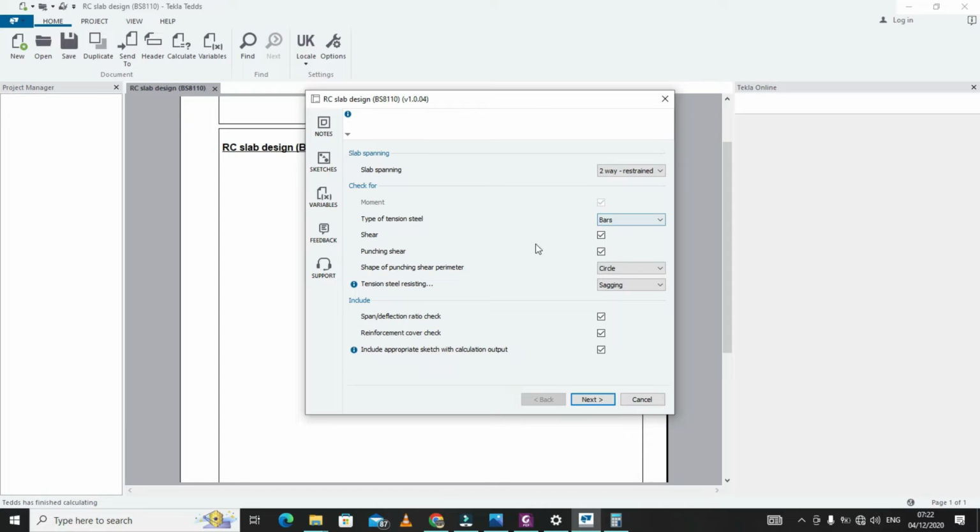For shear and punching shear, we shall not be using this, because for small panels of slab that are spanning for short distances and of very minimal depth, like the ones which we are using, they have very minimal shear. So we shall not go into determining whether we are putting shear, determining the shear forces and reinforcing for the same.